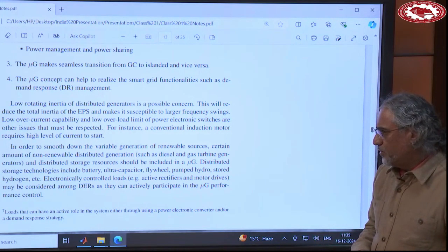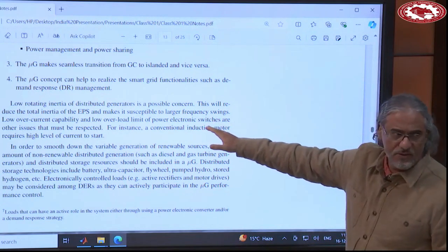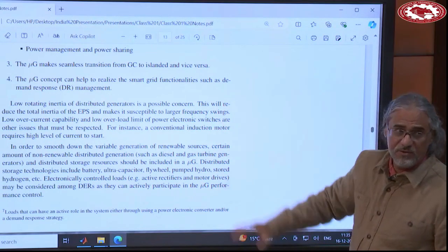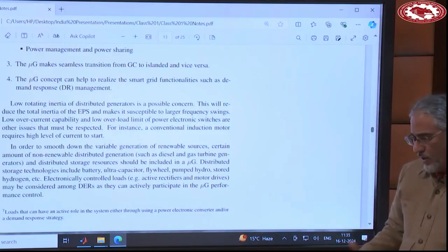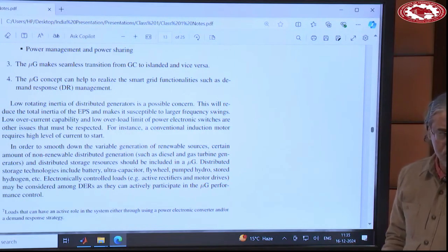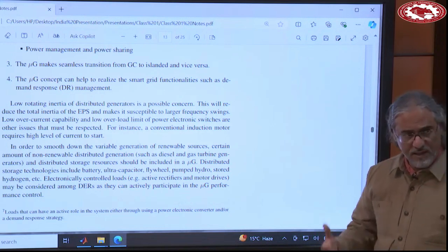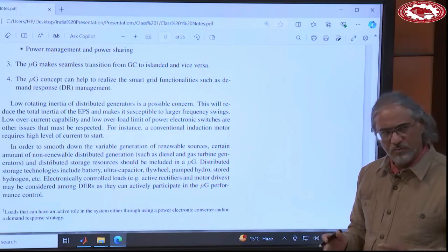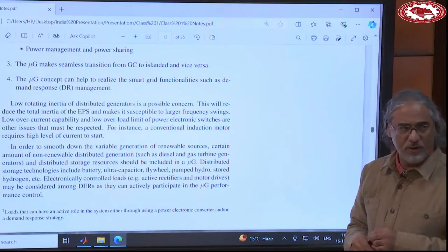So this whole power system is very much dependent on this inertia in terms of operation, stability, and even synchronization. So it's very important. When you now want to integrate more and more distributed generation, like solar photovoltaic and even wind, even though wind has a rotating mass, a rotor at the generator side, we almost never connect the wind turbine directly to the power grid.